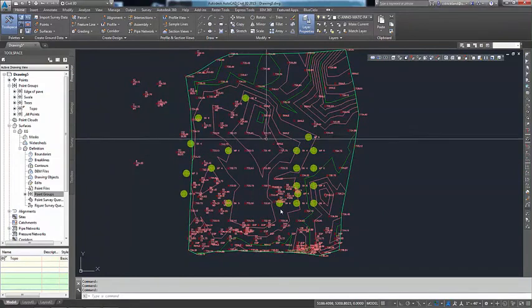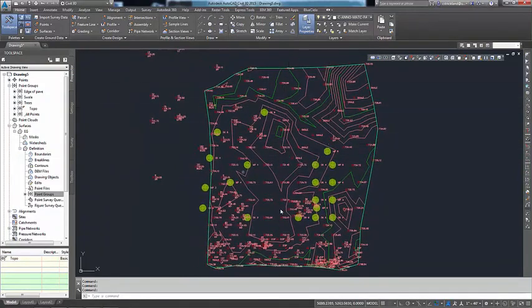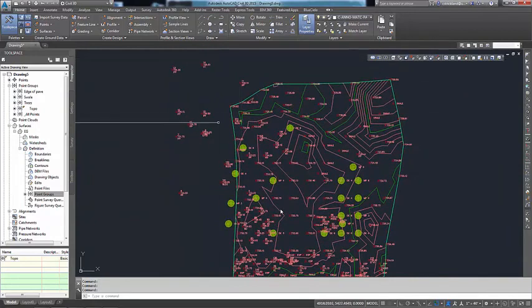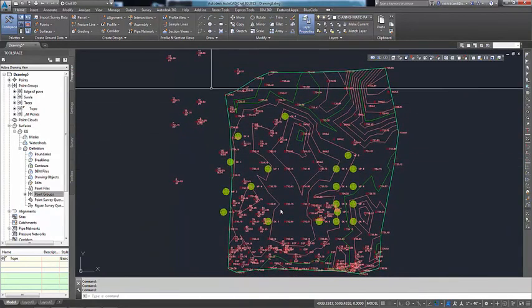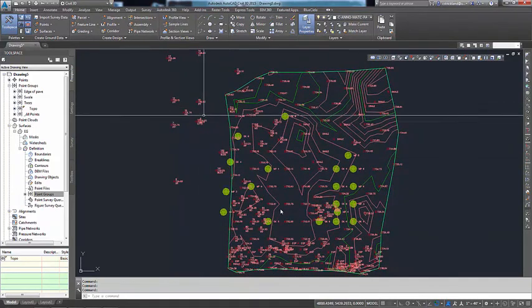And since my 1 in 5 design was built to give me some colored contours, that's what I got. There's the extent of all my topo points. It's put a nice little border on it. And everything that doesn't have a topo point in it is now left out kind of on the side. Those ones would be good to include in their own little hidden point group.